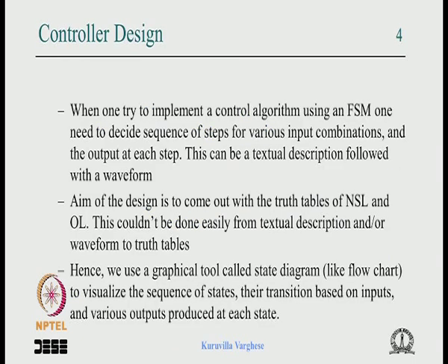We have looked at the controller design, and many times when we design a controller we have a text kind of specification, and from there we have to derive some set of sequences, then some waveform, but there may be quite a lot of possibilities we have to work out, and humans are always good at using graphical tools. So we use a graphical tool like a flowchart called a state diagram, which captures the various steps in sequence or states, and depending on the input its transition, and in each step or state what the outputs are. So that is basically what we are going to do.